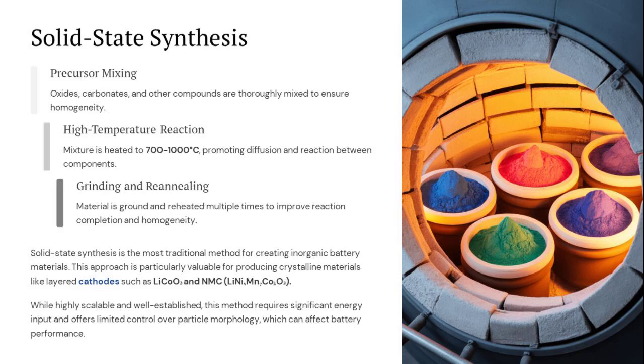Solid-state synthesis offers several advantages. It's well established, scalable, and can produce highly crystalline materials. However, it also has limitations: high energy consumption, limited control over particle morphology, and potential volatilization of certain elements during high-temperature processing. Recent advances in solid-state synthesis include innovations like co-doping strategies.